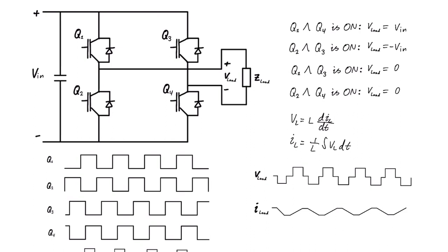So you maybe wonder what happens when the current here is constant, because then the switches Q3 and Q1 are on, which means that these two here are on, but they cannot flow any current here, right? So that means that the current, which initially is negative, continues flowing this way and goes through Q1, right? And there is a current also going from here through the diode into the load.